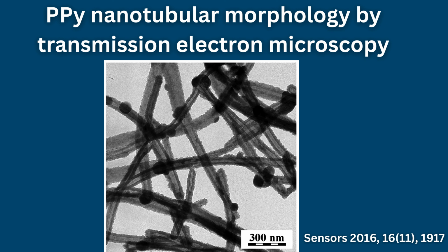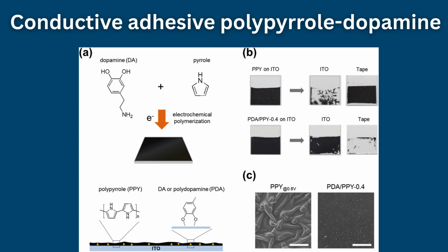However, beyond this concentration, aggregation of nanotubes occurs, which disrupts conductive pathways and increases resistivity. The improved conductivity results from the nanotubes acting as bridges connecting adjacent silver flakes, thereby reducing tunneling resistance. Such systems are particularly useful in flexible electronic devices. Dopamine-modified polypyrrole. Surface-modified conductive polymers can further improve filler dispersion.